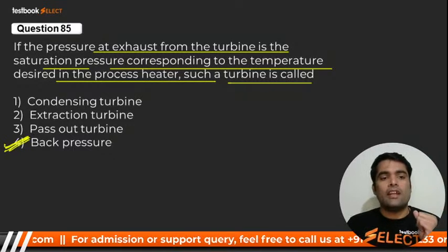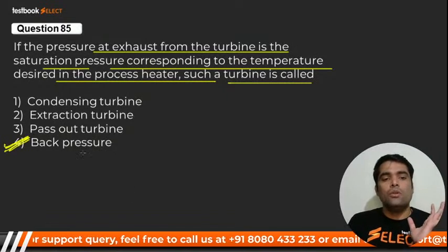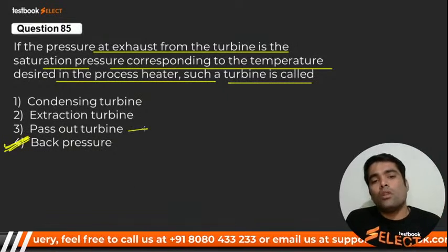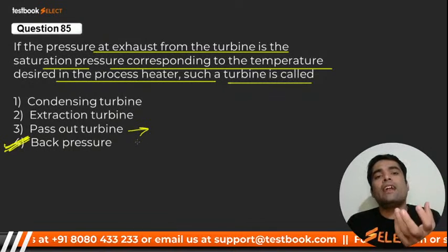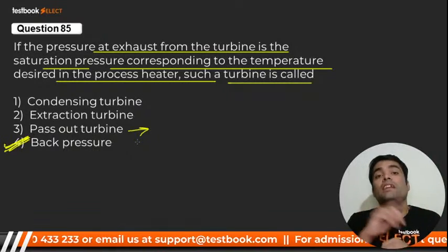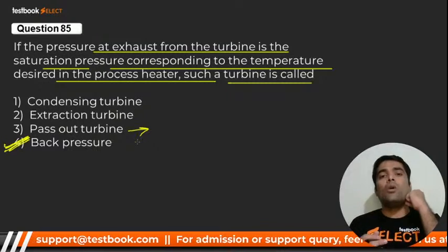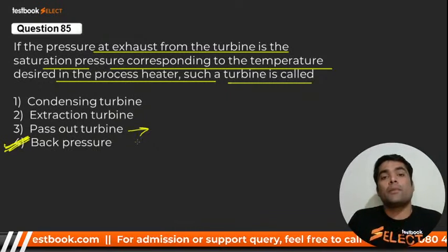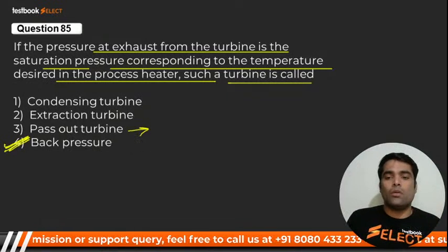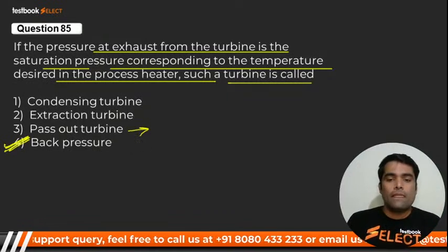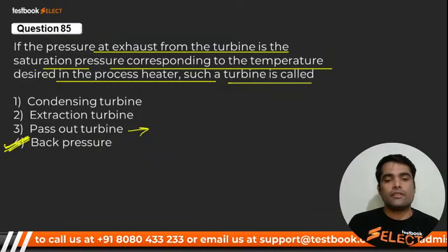Very good. Question 85. No, it's not extraction. I want to tell you, it is called a pass out turbine. The pass out turbine is a turbine from which we can draw the steam for heating purpose continuously from an intermediate state, where from the middle you can just take out some amount of heat for heating purpose. That is what, my dear? Pass out turbine. Okay, let's go ahead. Here we go for the next.